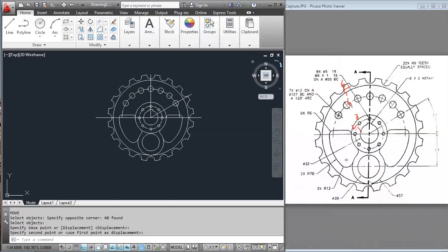And there are some dimensions that you can always calculate. Even the dimension for this circle was assumed, right? Circle number 3. But then the dimension for this circle could be calculated using this dimension and the radius of the center, radius of this circle, right? So some dimensions you can calculate, some dimensions you just have to assume, right?